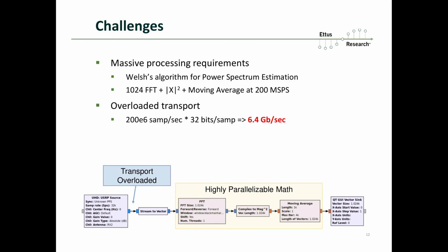This represents 6.4 gigabits per second, which is in itself a heavy load for the CPU to sustain. With such a heavy load as this, the CPU will face additional challenges around latency and determinism, which are often critical to some applications. It could become difficult to achieve precise timing and maintain proper data flow.